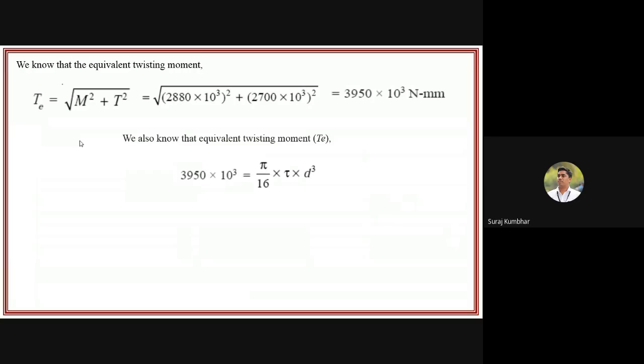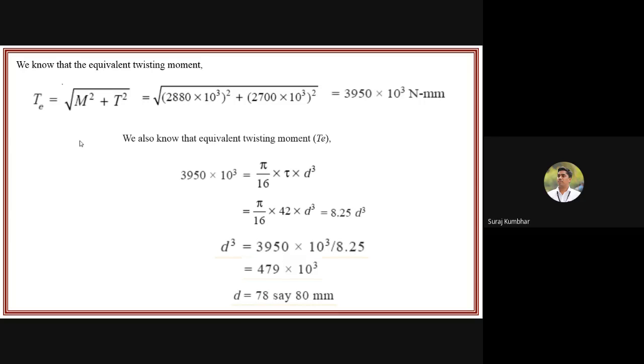Okay, Shivangini says 77.76 mm. Okay, we will check it. Okay, next, anyone, please post here the diameter you find. 78.26, 78.2. Okay, we'll cross check it. Okay, so diameter value is 78. Okay, so yes, it is correct. 78.26. Okay, it is correct, so it is an 80 mm shaft. So those who are getting a 78 point something value, it is correct.